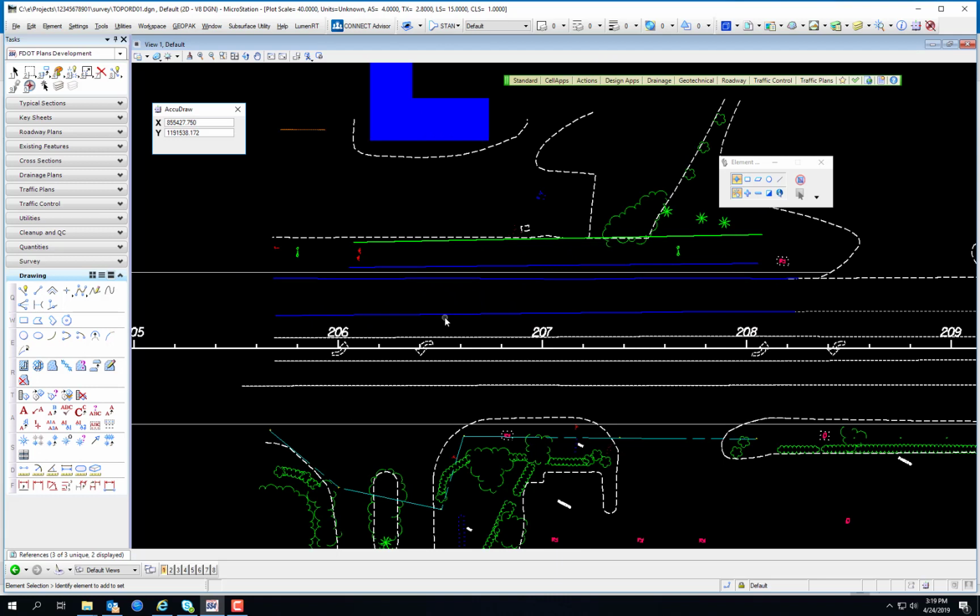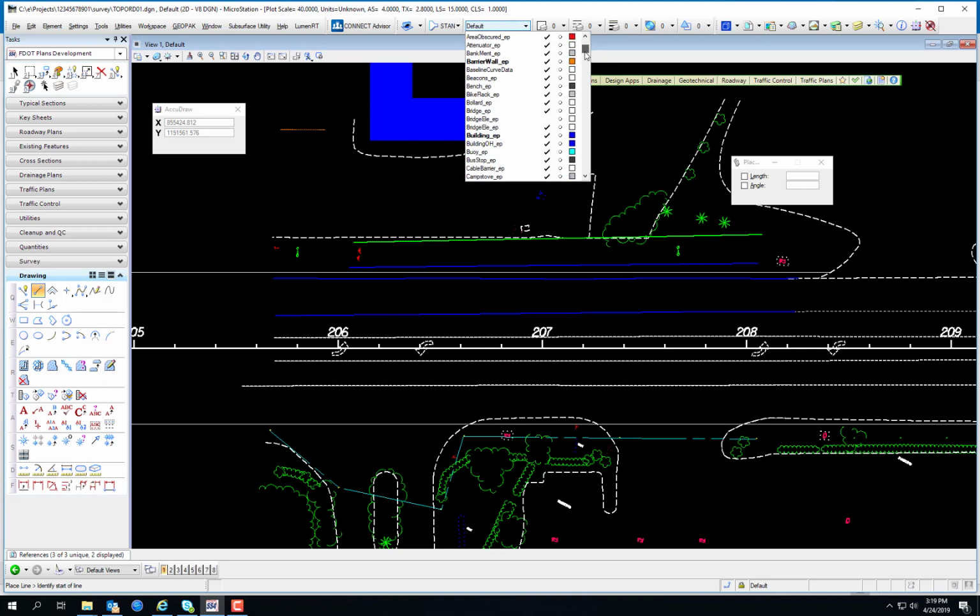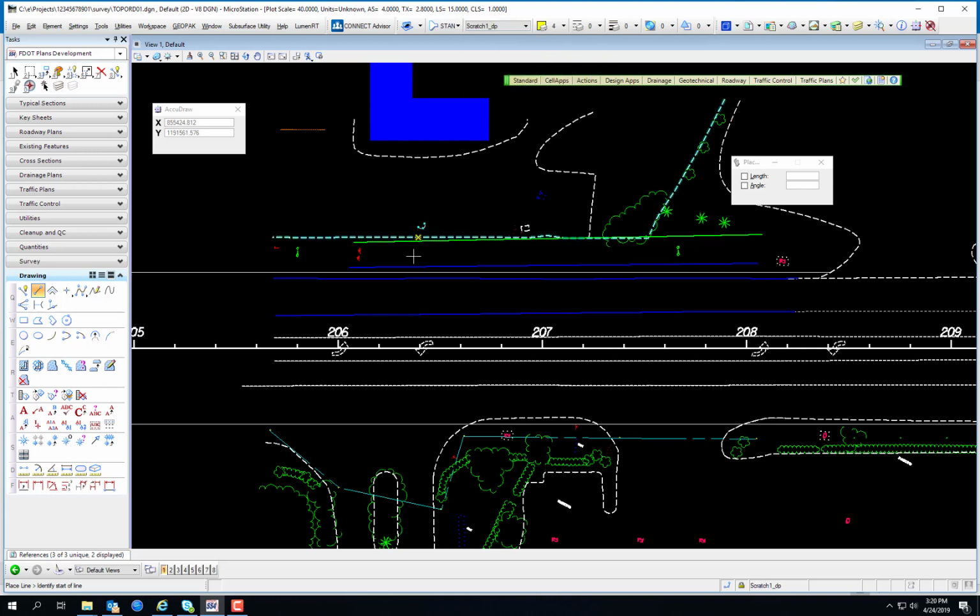Now in this exercise, they have us drawing a line using AccuDraw, and we're using that line as another point to snap to move the fire hydrant. I'm going to show you two ways to do this. The first way, they say, is to select Smart Line, and they say don't worry about what level you're drawing on in this case, because we're going to delete this line. It is just a construction element. So really what you could do is come down to a scratch level, because we're just drawing a scratch element.